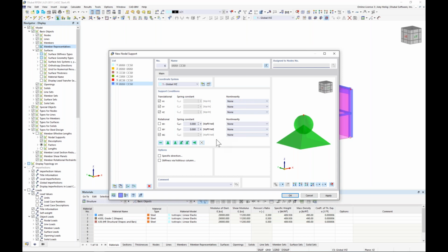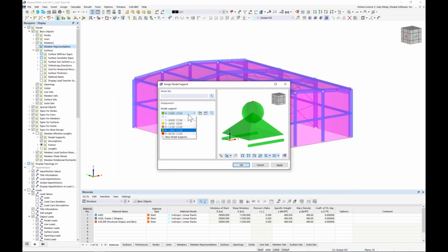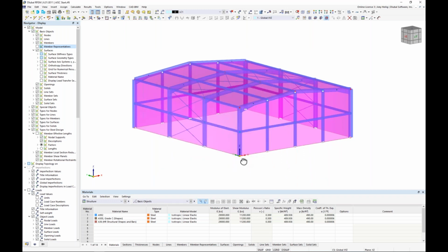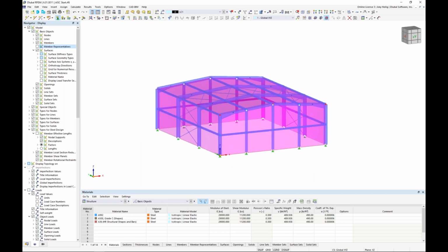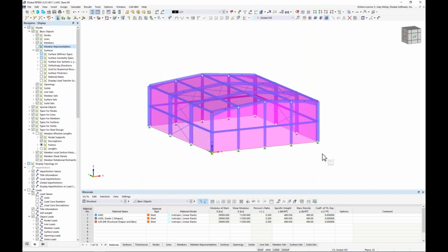So let's say we want it to fail and uplift. This is possible, sliding, friction. We can define those with those nonlinear options. For today, I just want to choose the default pin option here, and I click OK. So then this allows me to highlight over the bottom of all of my elements to apply that nodal support at the base of each column.